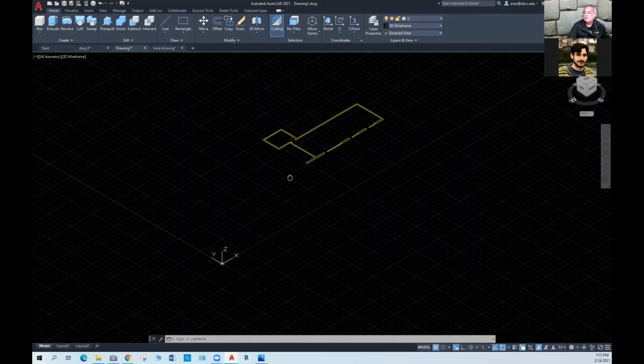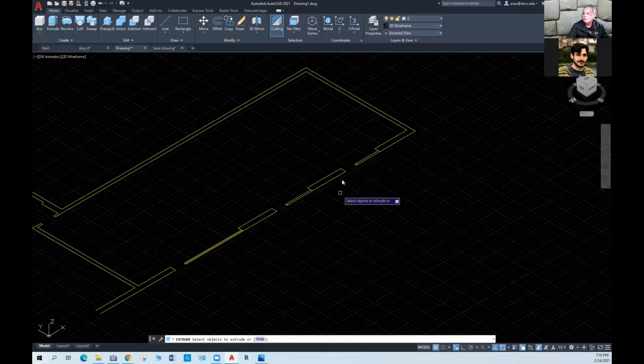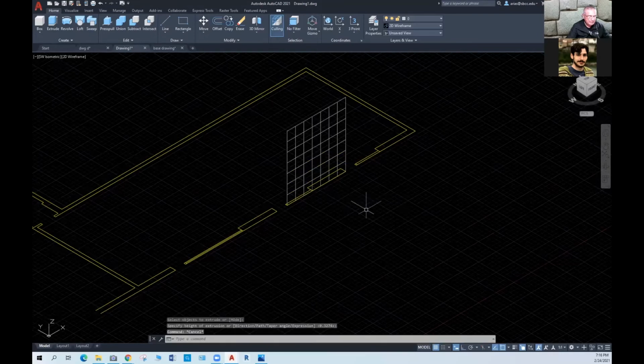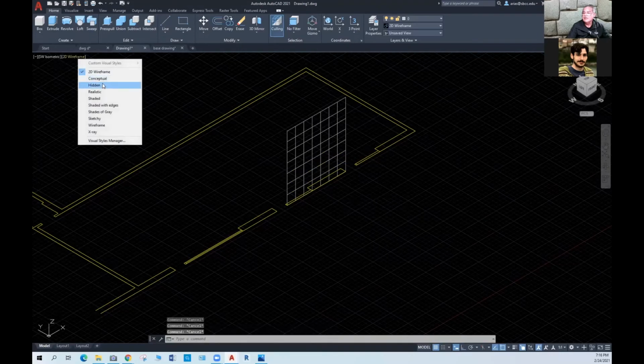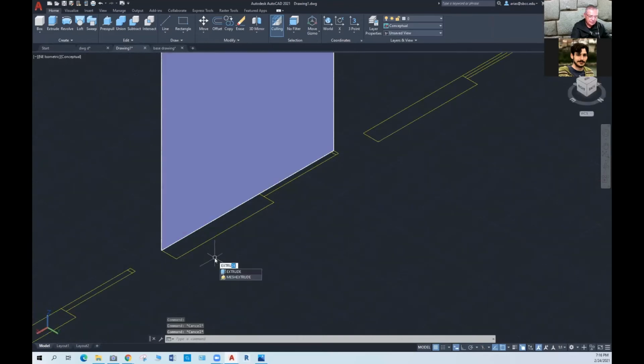So now that I have this plan view here, then I can apply some tools. I can apply some tools to create geometry. Can I apply extrude? Well, let's see. Yeah, I can, but remember that extrude on a single line element only creates a 3D face. Even though the 3D face is the right size, it's just a face, right? So I could continue to do extrude and select all of the faces, right?